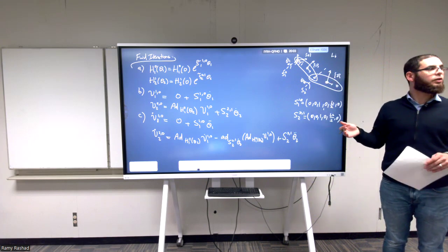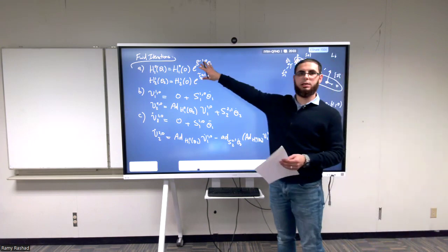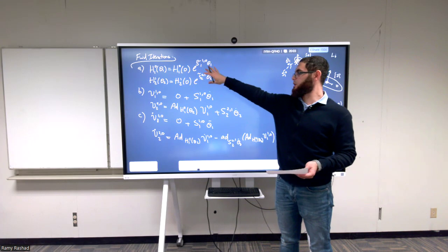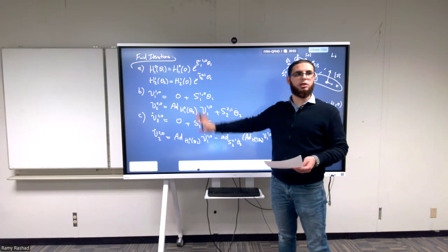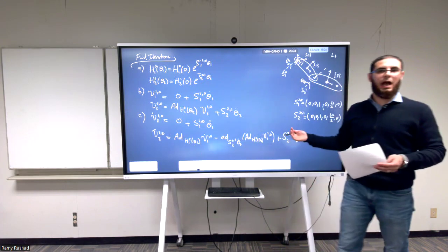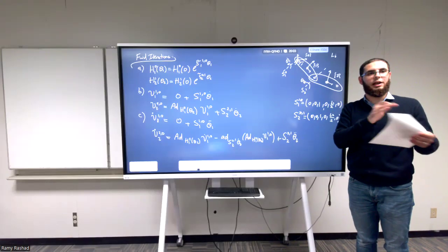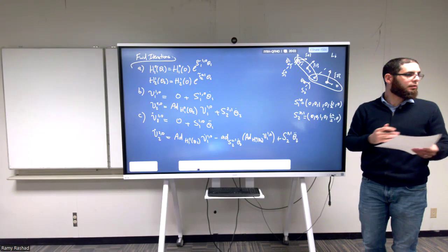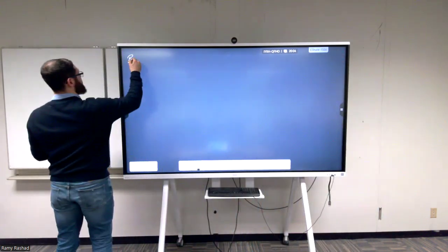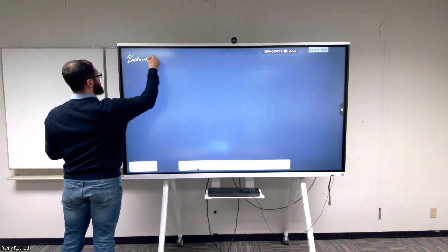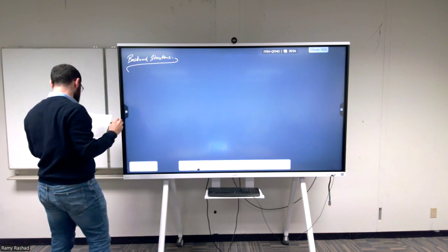Right? In the backward iteration, we're going to calculate the wrenches and the torque. So everything here, you can think about, this is just the poses, the homogeneous transformations. This is the velocities, and this is the acceleration. So position, velocity, acceleration. What we're going to be calculating now is the relation between the wrenches, which is the co-vector equation, the wrenches and the momentums and everything, and the torques. So the backward iteration,